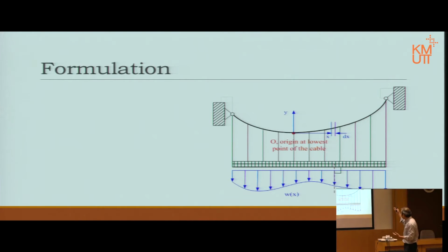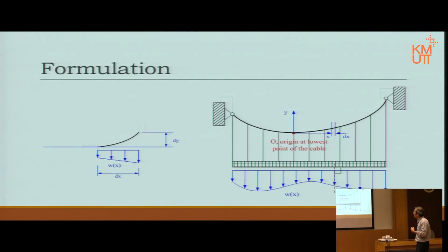Now, once we choose a part of it, as I said, we assume that the load W at the bottom, the blue, is subject directly to that part of the cable itself. So basically we transfer it into that picture there. Notice that this small piece of the cable is not assumed to be a straight line, because if you assume a straight line, it means the same tension throughout, which is not quite true in this case.